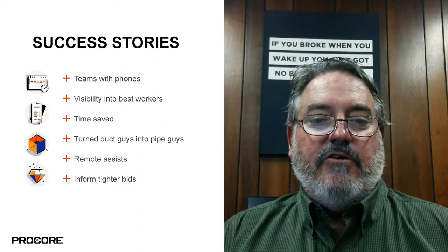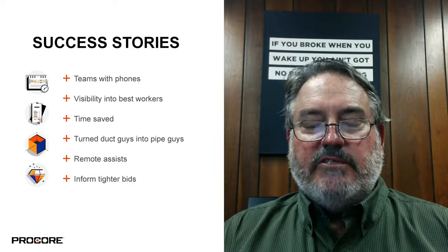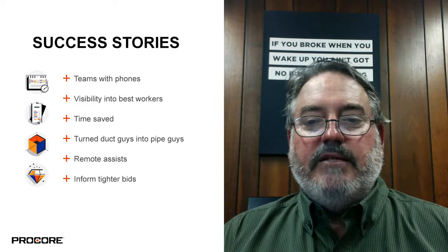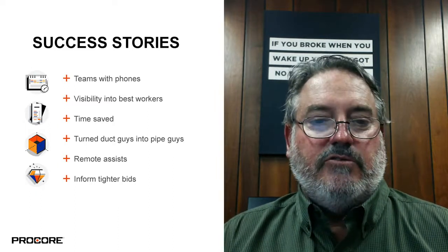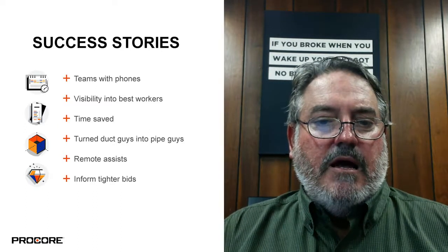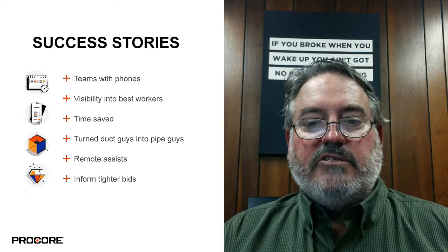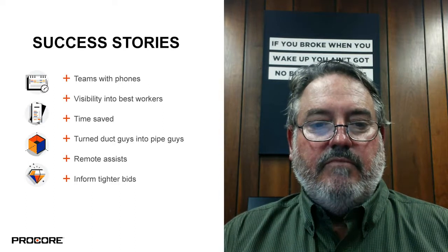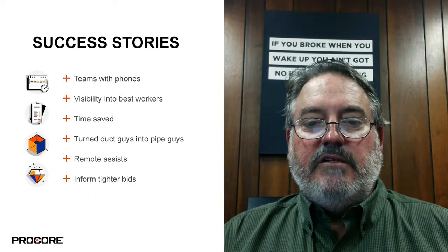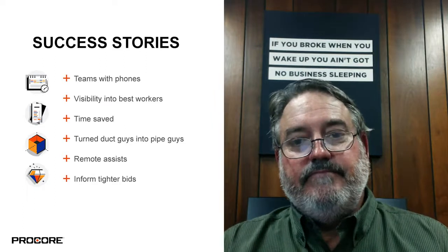Cross-training. Since we have such great models, we're able to do assembly now. It's not a specialty trade as much as it used to be. We can actually train sheet metal workers to install piping and train pipe installers to install ductwork. They just know everything fits. We just have to teach them how to use the tools. All piping and ductwork are modeled, labeled, and prefabricated. There's no question about where it goes. You just search the model. We also have real-time discussion with stakeholders about the need to physically show up on a project and disrupt production.